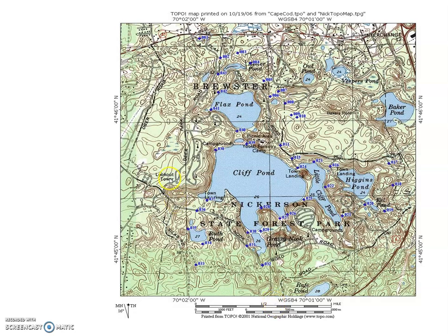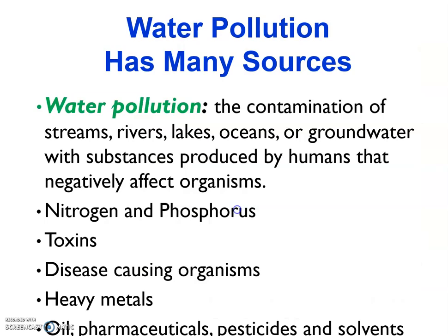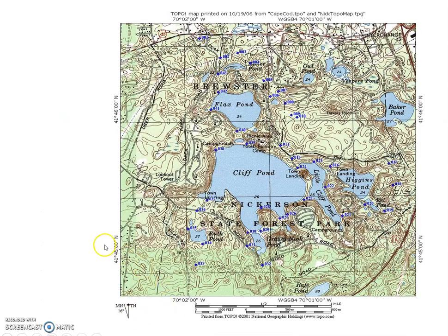Then you go to your Lookout Tower, pretend you put a well there, and let's say your measurement brought you to, say, here. Put a dot here. Then move your ruler around to another 0.6 mile mark, put your point. Whoops, let's go back. And so forth. And you'll eventually get some dots that you can connect in a nice smooth circle. Okay? That is your recharge area, and it will go off your map. I mean, the map just doesn't have Lookout Tower right in the middle.